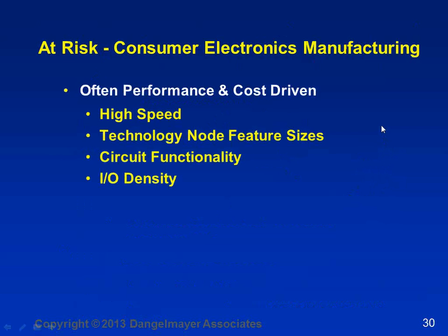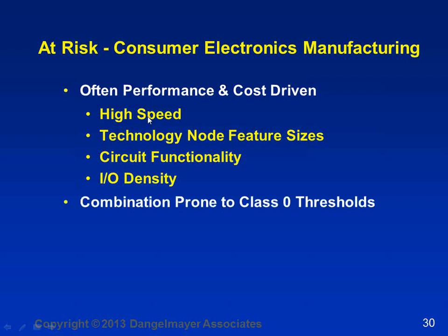Okay, consumer electronics. They tend to be cost-driven, performance-driven, all the things that you and I want. Cell phones, smartphones, with high speed, etc. All of these things tend to aggravate the ESD sensitivity. And the combination is prone to class 0 thresholds and, of course, charged board event issues.